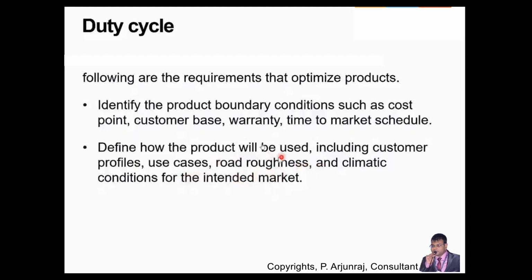So we also do different types of tests like city condition test, highway condition, rough road condition, accelerated durability condition. A lot of conditions where we test the vehicle, and various different climatic conditions. That's where we also do some of the hard climatic tests, things like summer dryer, winter dryer, especially for electric vehicle aspects, where the summer dryer is very important to ensure against thermal runaway, or to understand what range they are going to get.